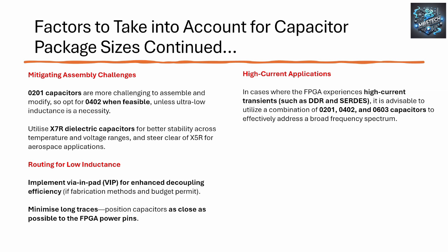But even so, you should still be able to meet all the decoupling placement requirements on that type of card. It only gets more challenging when your pitch size goes down. And if the pitch size goes down, then the capacitor, the FPGA part size goes down. So you might have to use blind and buried at that point, and so forth.